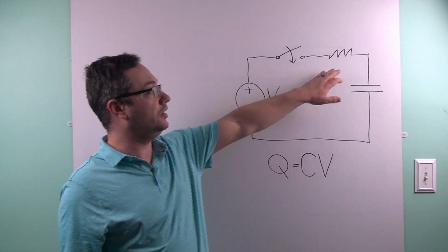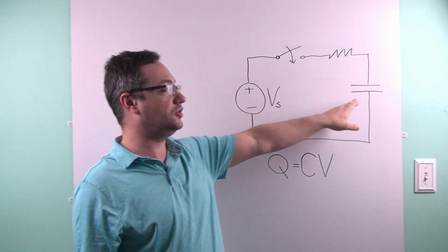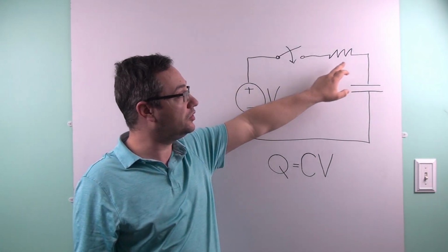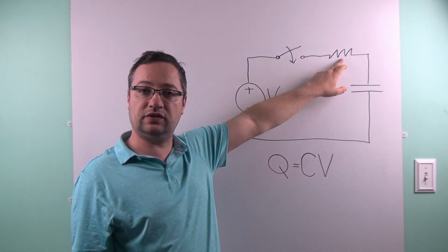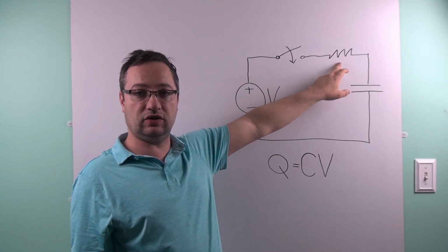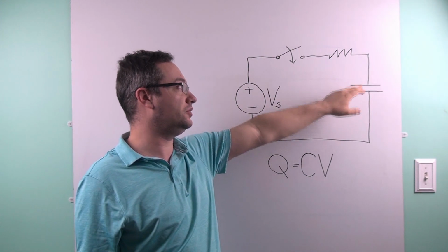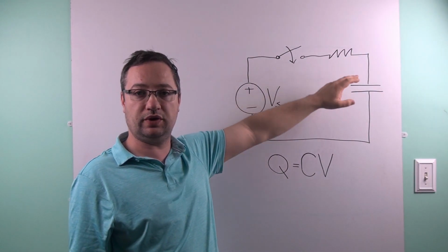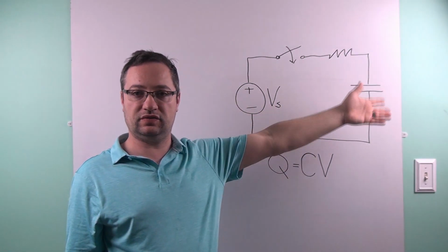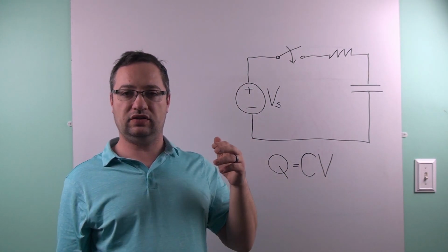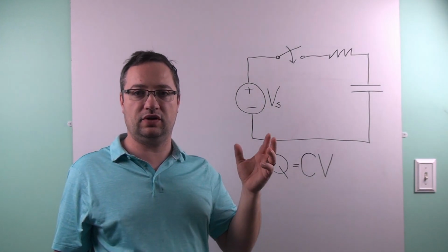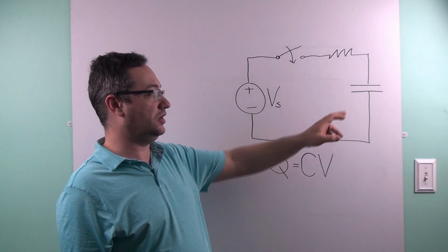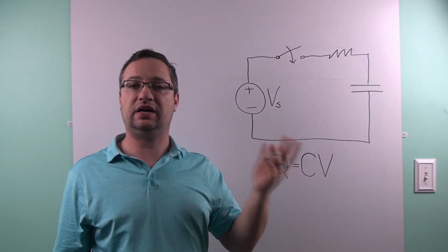The reason this model has a resistor here instead of just having the voltage source, the switch, and the capacitor is that, as we looked at a little bit ago, the capacitor always has some type of resistance in it. And so this resistor can be the effective series resistance of the capacitor, or it can be a garden variety resistor, which is a bulk element combined with the effective series resistance, or it can be just any old resistor, which is so large compared to the effective series resistance of the capacitor that the ESR can effectively be ignored, because ESR tends to be very low in the sub 1 ohm area, like 50 milliohms, 500 milliohms. And this resistor could be, you know, a mega ohm. And at a mega ohm, a million ohms, 50 milliohms of effective series resistance is entirely negligible.